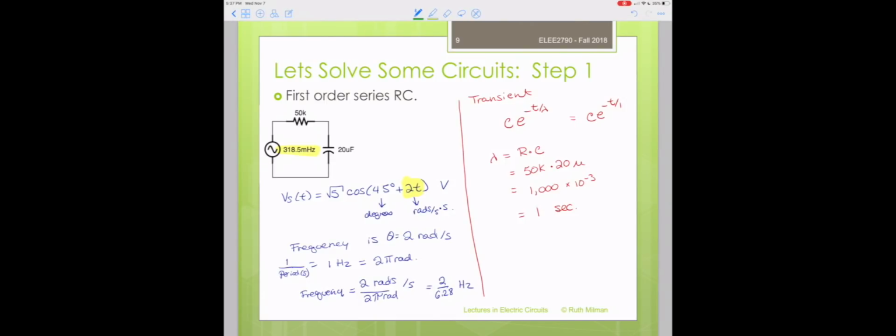And that's an understanding of the initial conditions, because we're never going to get to the bottom of what any of this means if we don't know what the actual initial conditions are. So let's talk about initial conditions. You're typically going to assume that this source is off until time 0. So everything in the circuit is off, which means that initially the voltage in the capacitor is equal to 0. And I'm just going to make sure that that's clear, that the voltage in the capacitor from the left is equal to 0. But in a capacitor, we have particular equations that define how the capacitor works.